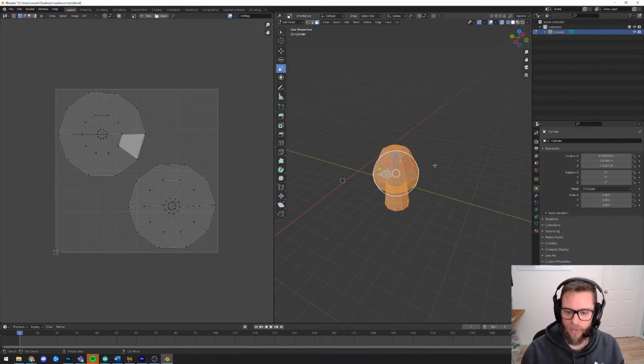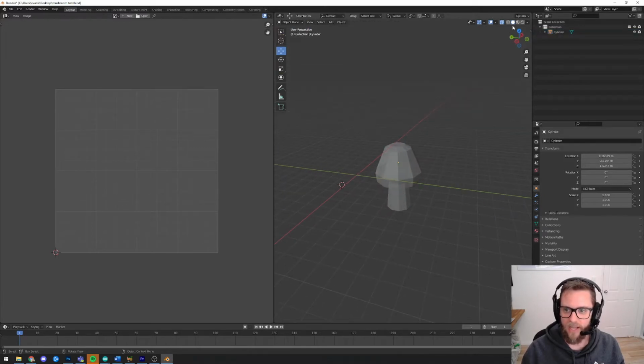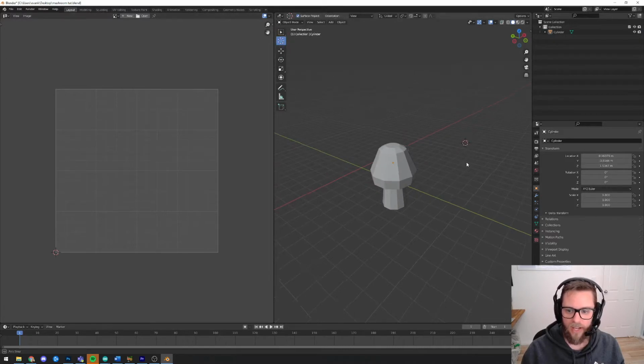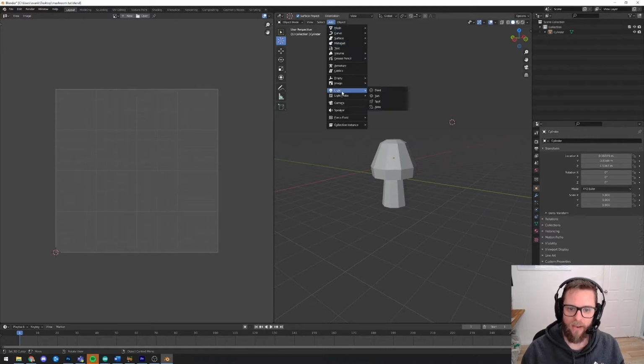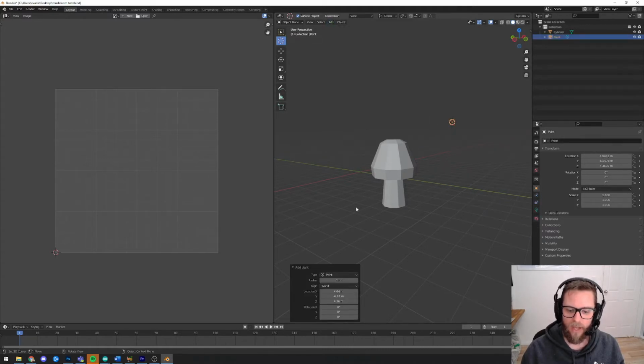One of the first things that we're going to have to do is create lights in our environment here. If we don't have the lights, when we start painting on here, things aren't going to show up properly. So what we need to do is grab our 3D cursor and position it up in the sky at a particular point, and then we're going to choose Add Light Point, and it should insert wherever your cursor is currently present.